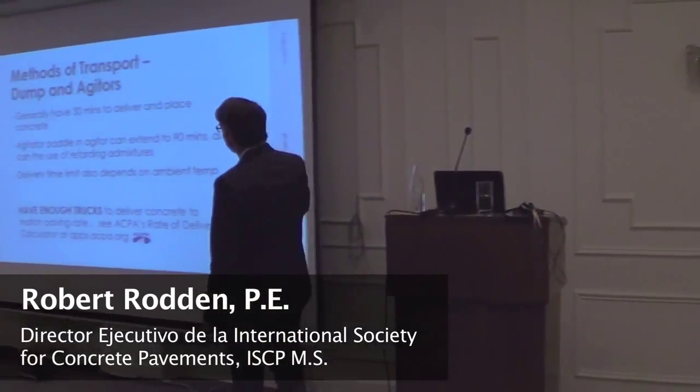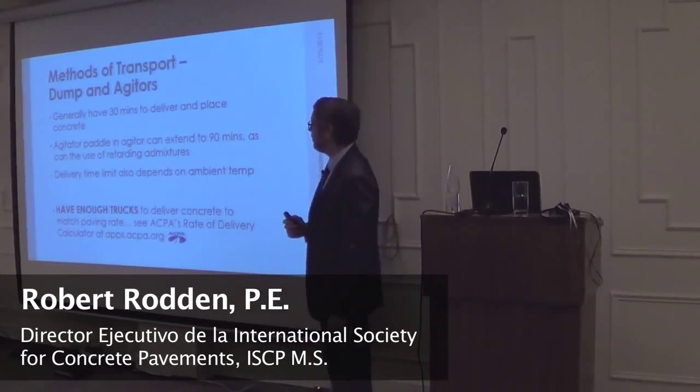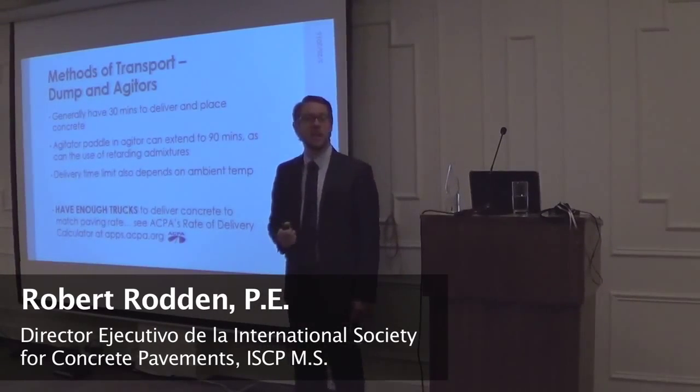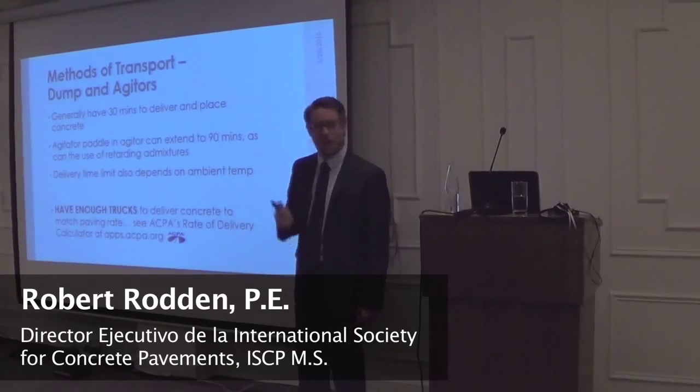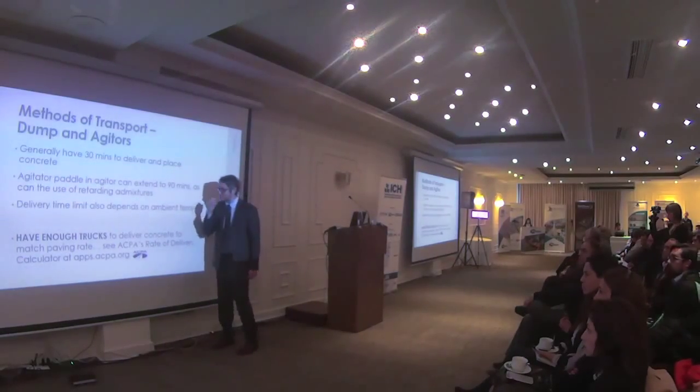So those agitator paddles can extend that delivery time to about 90 minutes, as can the use of some retarding admixtures. They just slow down the hydration, give us more time to deliver. Delivery time also depends on the ambient temperature.